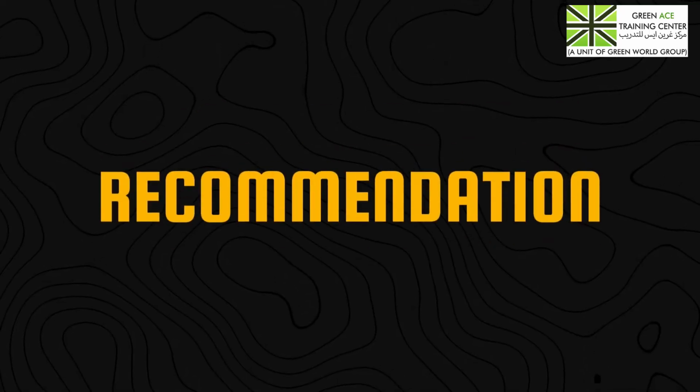And the last part is documentation. Finally, after doing all these studies, everything has to be recorded: findings, team discussions, recommendations and responsibilities. Responsibilities means whatever we have suggested has to be done by some responsible people, so who those people are, we will record it. Due dates are also assigned, and a formal HAZOP audit report is generated, which will be handed over to the team. This document serves as the official record of the audit. So these are the 6 important points about the process of conducting a HAZOP audit.